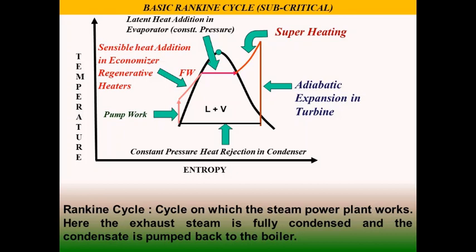In the drum we have a separating arrangement, and due to this, dry saturated steam comes out of the drum and goes for superheating, and superheating takes place in different phases.